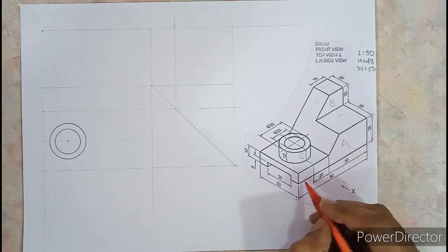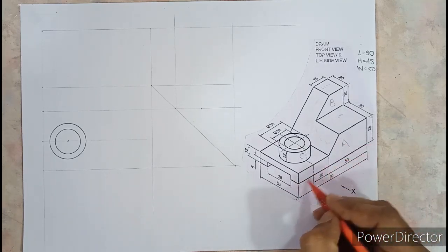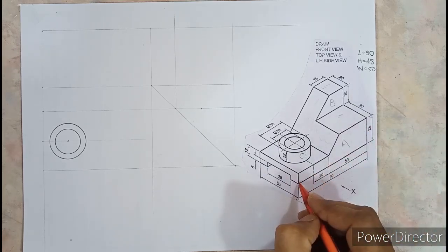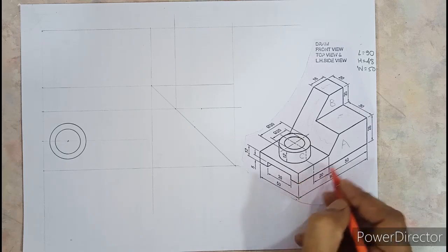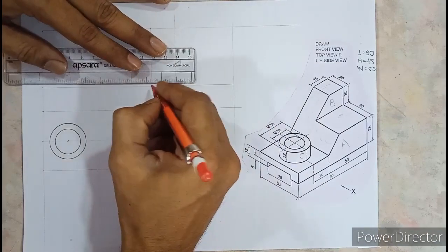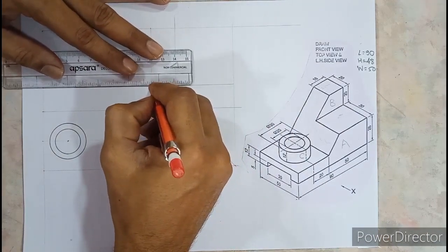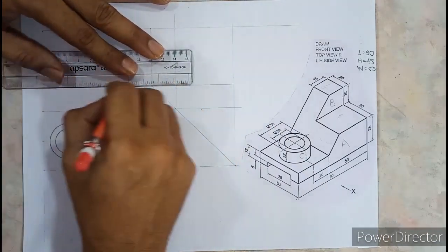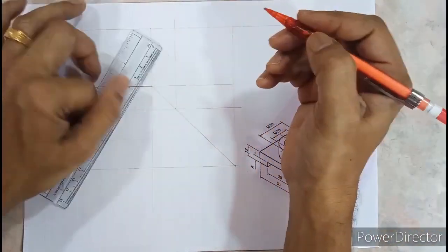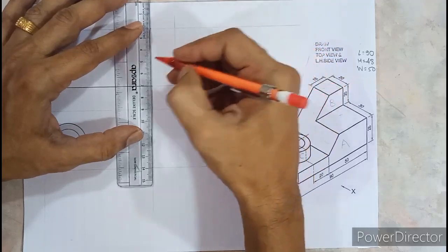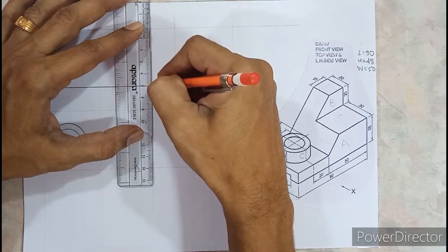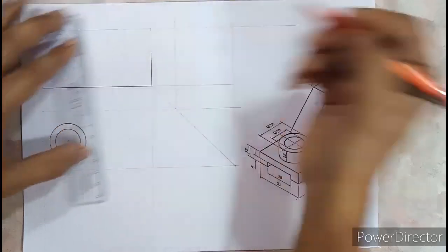Let us start with A now. If you look at A, you can see a dark line of 90 mm long. Then you can see 20 mm long line upward, and on this side it is 12 mm upward. So let us first draw these three lines. So to begin with, first we will start from here. Those lines should be drawn dark, so double trace, left to right, right to left. Then 28 mm up you have to move. So from here we'll move up by 28. Yes, that is what we have done.